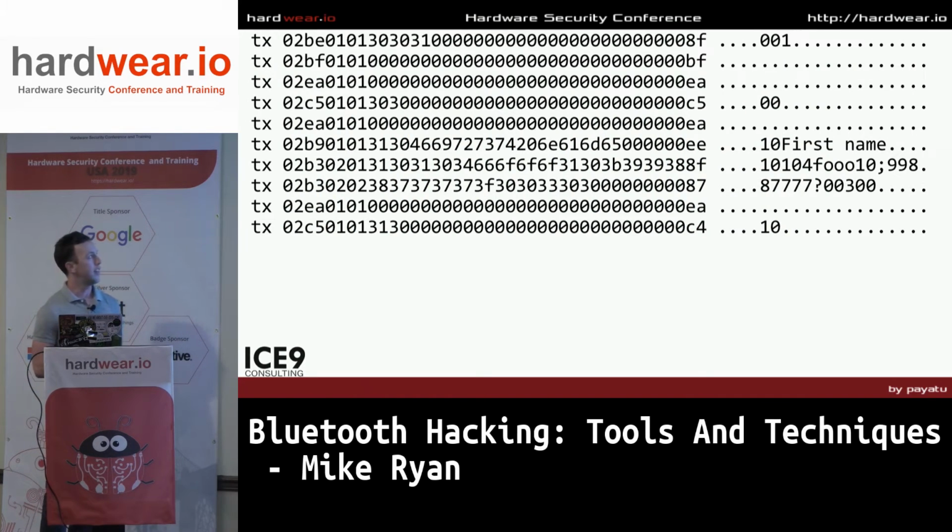you can see you get a bunch of messages, and they all have a really predictable structure, and you can even start to see some unencrypted data, or well, it's not encrypted yet, some ASCII data here. One of these is a fake credit card number that I injected into the app. So now you can actually see the credit card data that's being sent over Bluetooth